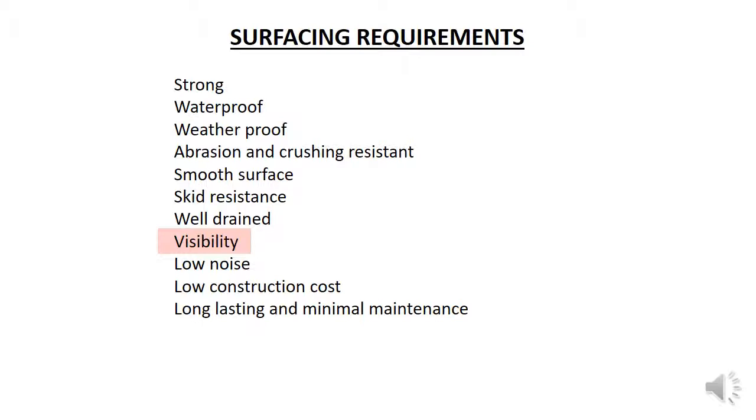Visibility is another important issue on the road. The surfacing needs to minimize glare and reflection from the road surface. The surface markings also need to be visible in all conditions to allow drivers to stay within their lanes. The surface also needs to minimize spray generation. Excess spray coming up off the road can hinder vision for the following vehicles and those going the other way. The main way this is done is by reducing the water on the road using good drainage. The coarse surface textures can also reduce the spray produced from the road.